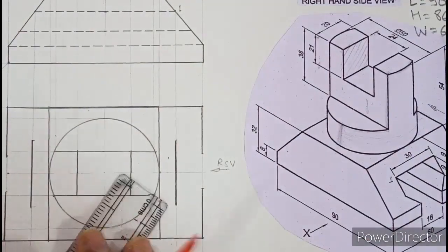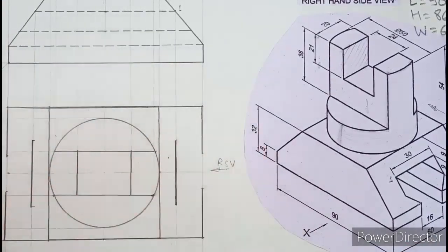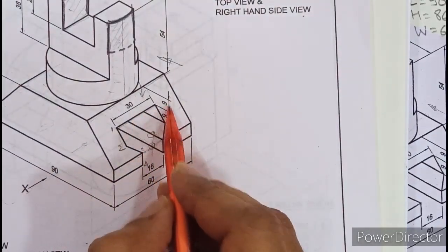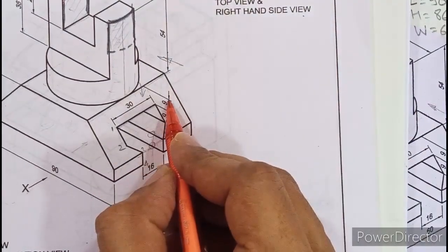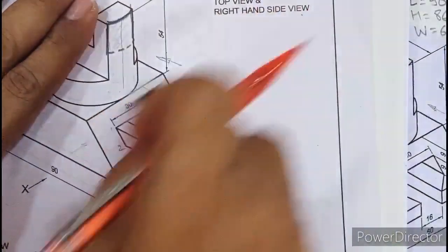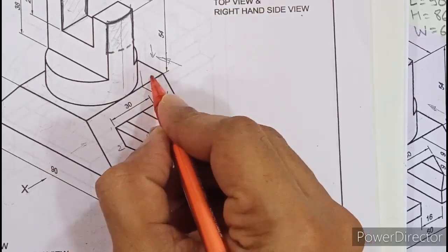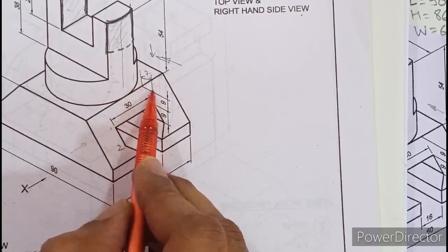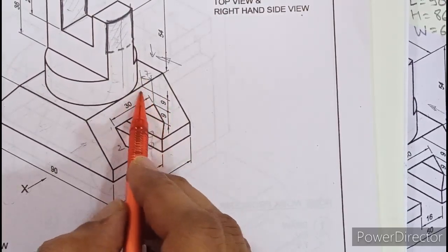So one thing to be noted, if you note down this dimension between these two dark lines, it is only 7, and in the question this is given 9. How come? So the point to be understood is this 9 is a vertical dimension, and then what is 7? So if you look in the top view from here, if you project this point and this point, the projected length is 7, and obviously the projected length has to be less than the vertical length. See, vertical length is a true length 9, but the projected length is only 7.